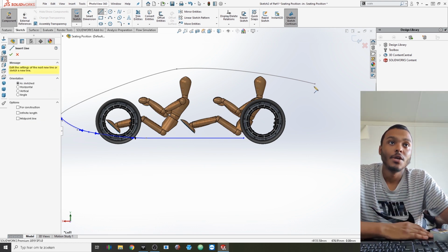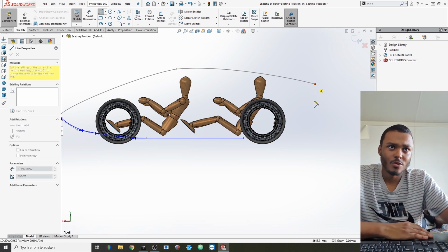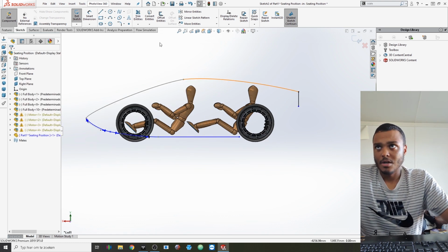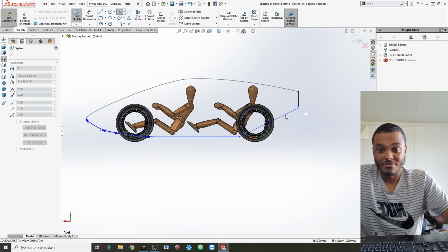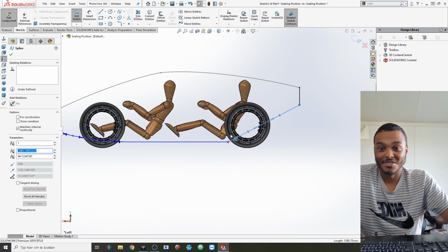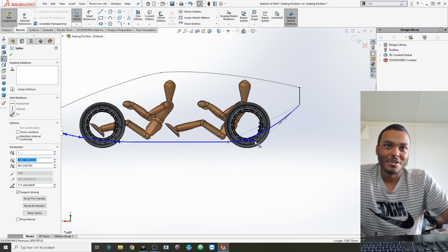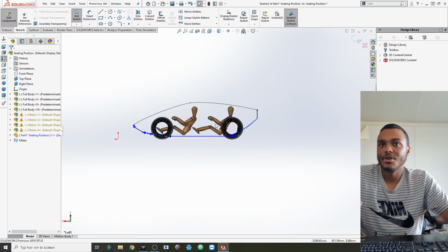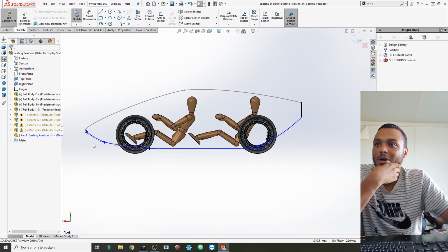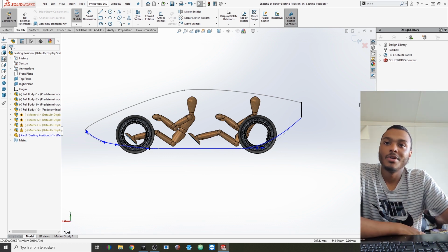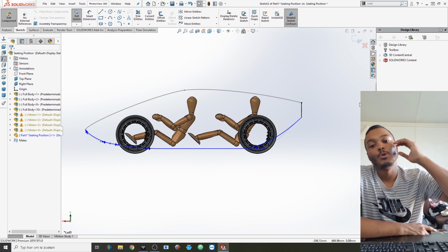But for this car, I am going to make it a little bit more of a station wagon type deal, giving it a bit more of a back surface, and then still make a very extreme diffuser at the rear, because that would just look amazing if you ask me. That is what I want to do here still. Also, if you add a curvature, a round surface, to the bottom of a car that is very similar to the round surface on top of the car, that will help eliminate a lot of the natural lift that a car will produce.